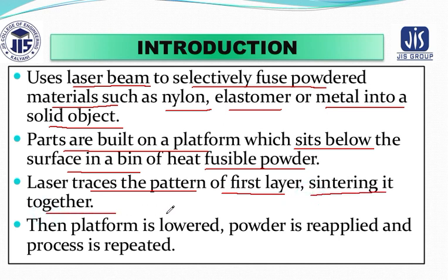Then the platform is lowered, the powder is reapplied, and the process is repeated. You can see how selective laser sintering plays an important role in producing the part.